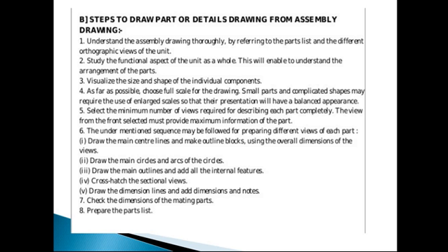Because in a detailed drawing there may be a number of components, if you draw with minimum views, every component can be accommodated in the same sheet. So this is the main important thing. And in the front view, try to give as much detail as possible about the dimensions and the component, so that anyone can understand.